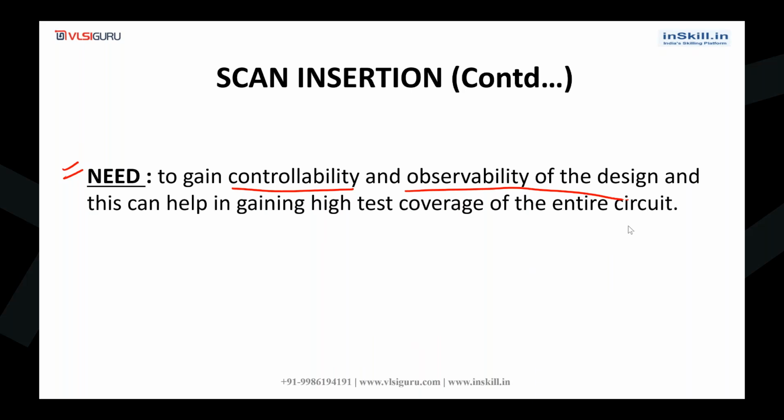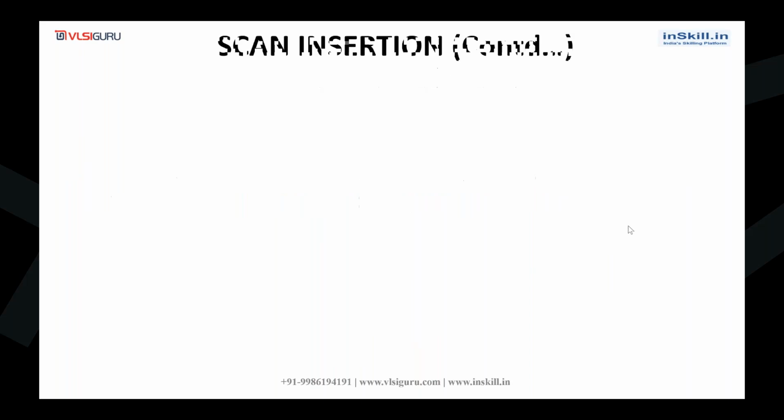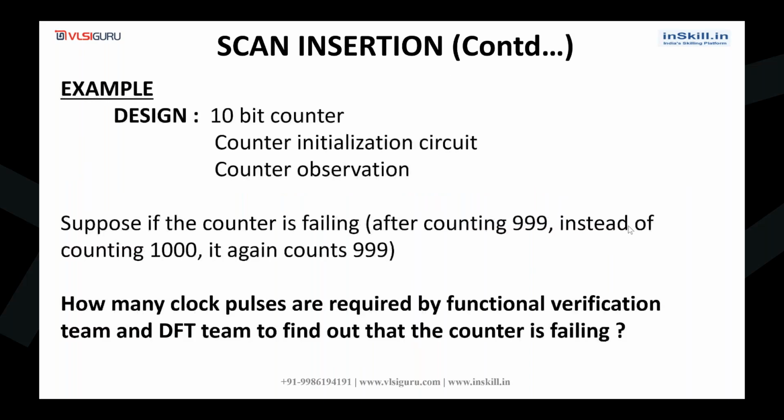The example to understand the need of scan insertion is the same counter example which we had taken in the previous slide. In my design, I have a 10-bit counter with a counter initialization and a counter observation circuit. Suppose the counter is failing, which means after counting 999, instead of counting 1000, it again counts 999.